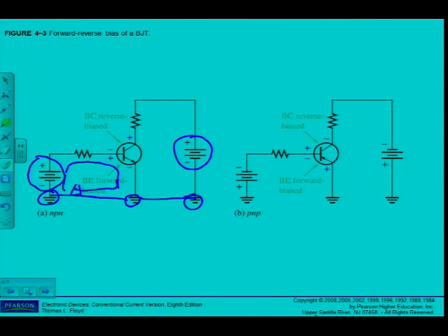I basically have, remember, two PN junctions, three materials, NPN. I'm looking at the NPN firstly. So what do I have here? It's N, P, N, so it's P and N. And you've learned to forward bias a diode, I apply a positive voltage to the P-type material, so the PN junction in this case is forward biased, and as you have learned, I should have approximately 0.7 volt drop over that forward biased PN junction.